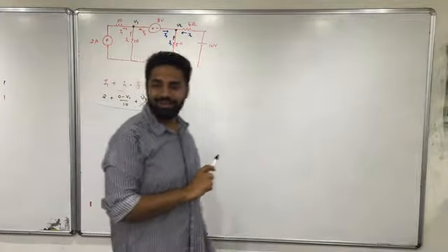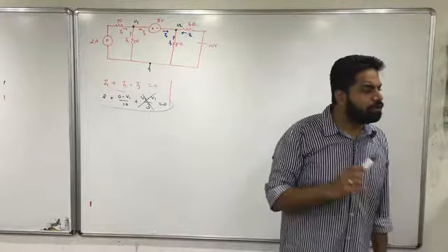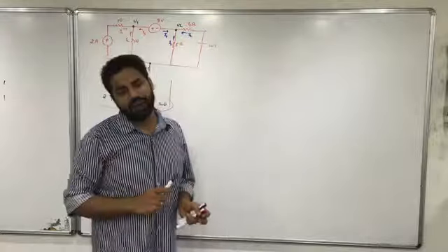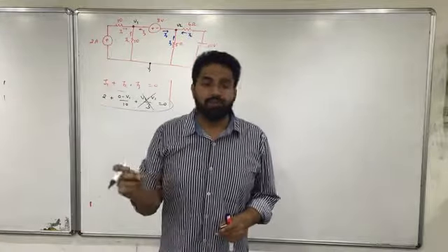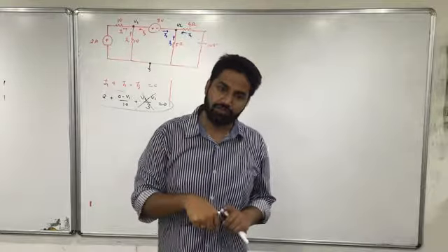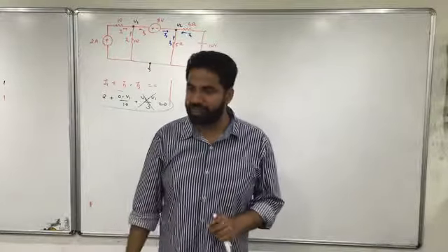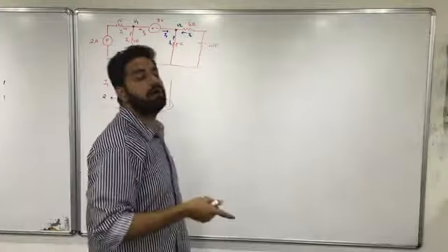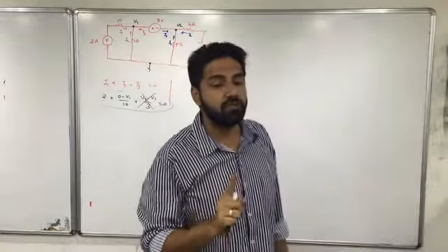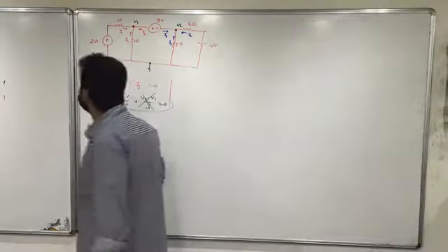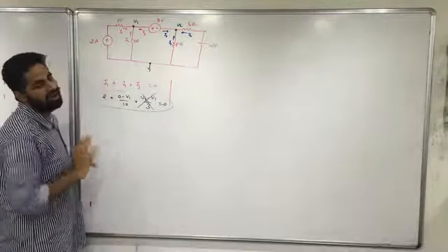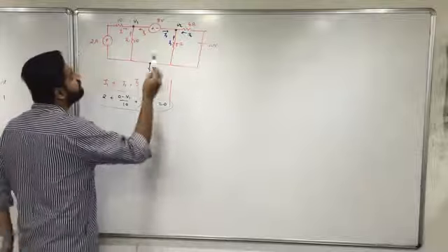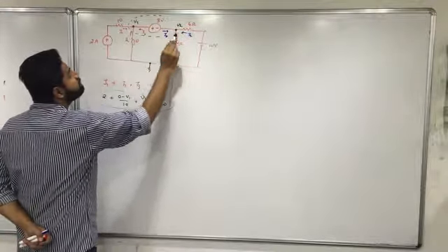Do you understand this? What kind of mistakes people are making? So how is this example different? Fine. So in KVL, in mesh analysis, we have understood one thing, that if in between two loops we have a current source, then that entire thing becomes a super mesh, right? Similarly, if in between two nodes we have a voltage source, that becomes a super node. Do you understand? Fine. So if it is a super node, you cannot solve it conventionally. So what to do for solving this kind of example? So this is the portion that we consider as a super node.